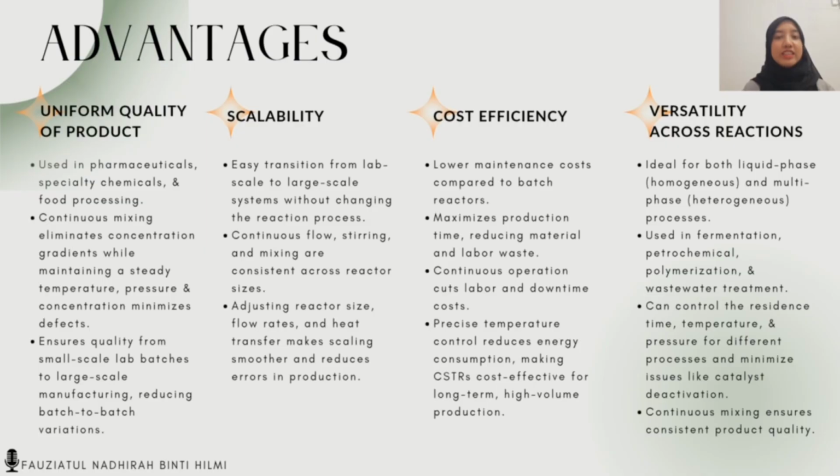Next are the advantages of the continuous stirred reactor. Firstly, the uniform quality of the product. It is used in pharmaceutical, specialty chemical, and fruit processing because continuous mixing eliminates concentration gradients while maintaining a steady temperature, pressure, and concentration that can minimize the effect on the product.